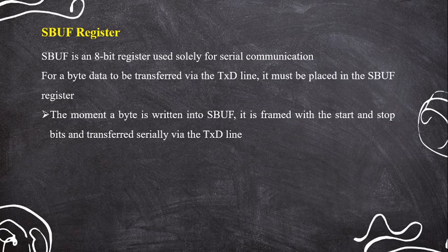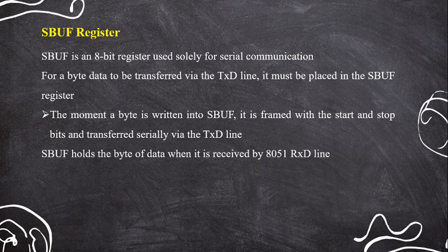What is that framing? It is nothing but having a start bit and a stop bit, in between which you have the information of the data. SBUF also holds the data that has to be received by the 8051. So this SBUF register is a common register used either for transmitting data from the 8051 externally or for receiving data by the 8051 from an external line.